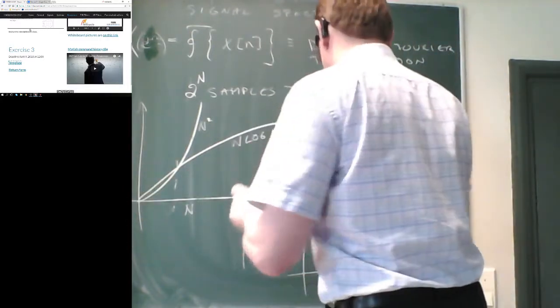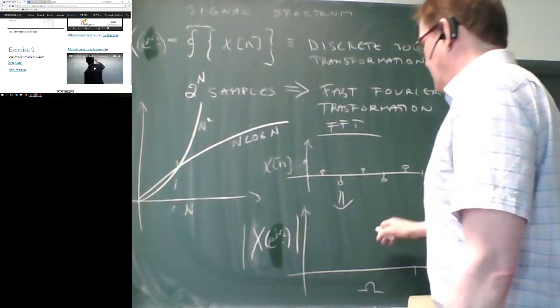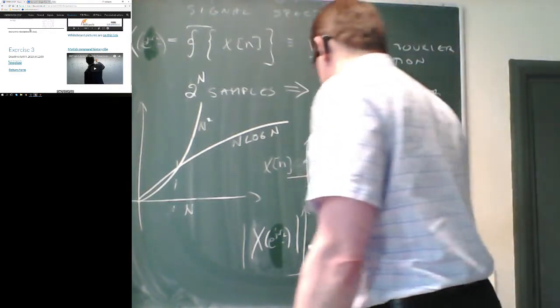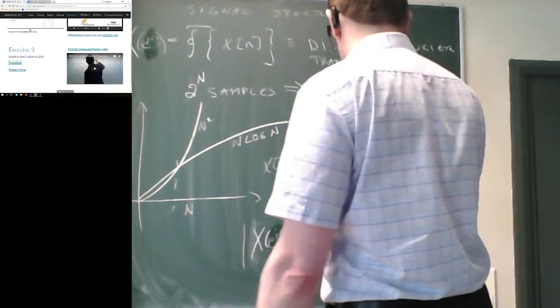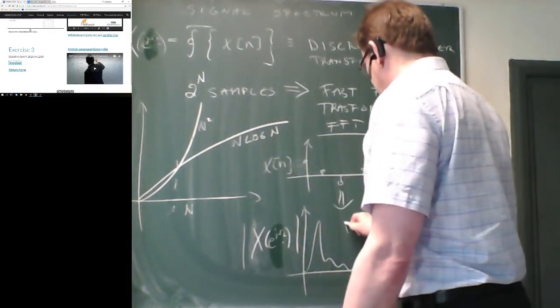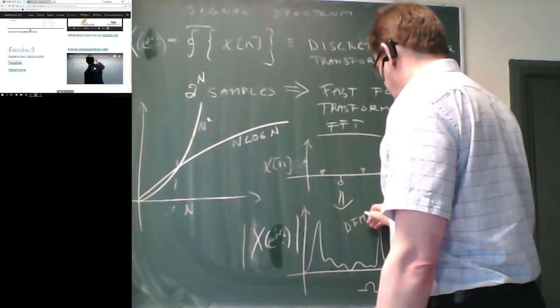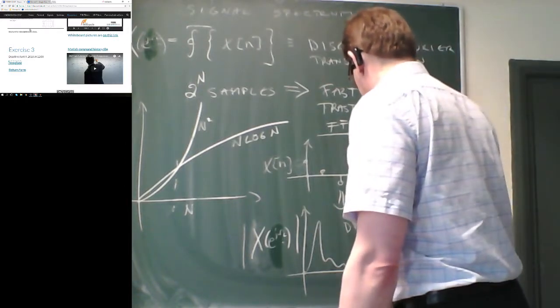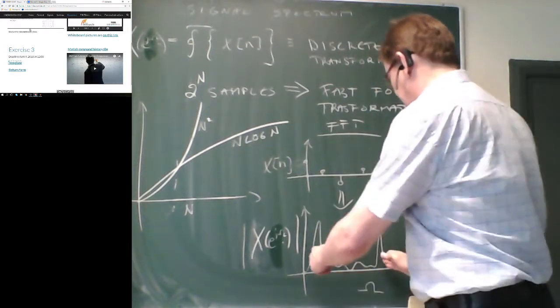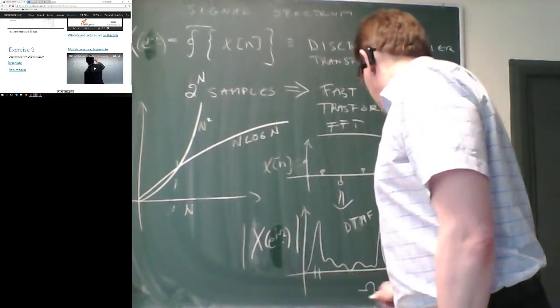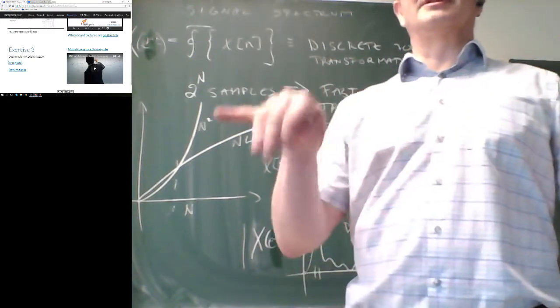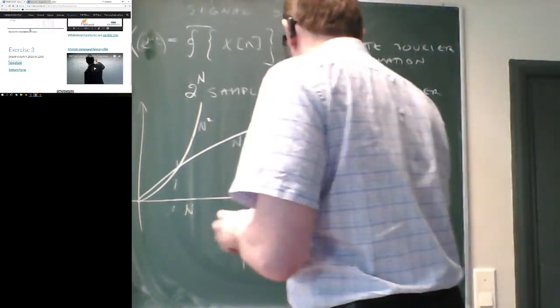So the amplitude spectrum of this signal would look whatever it looks like. For example, this could be a DTMF, dual tone multiple frequency, sampled data, showing we have these two signals there, and the frequency of those would tell you what the key code is for that DTMF signal.